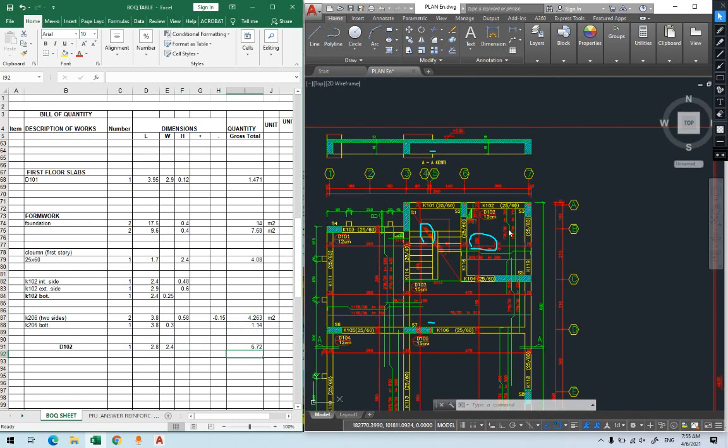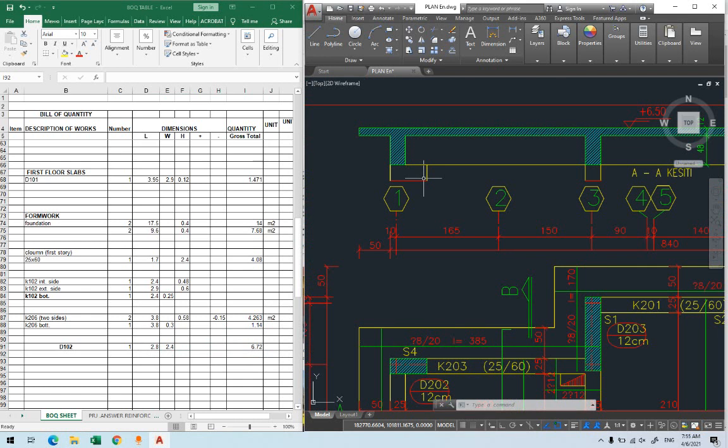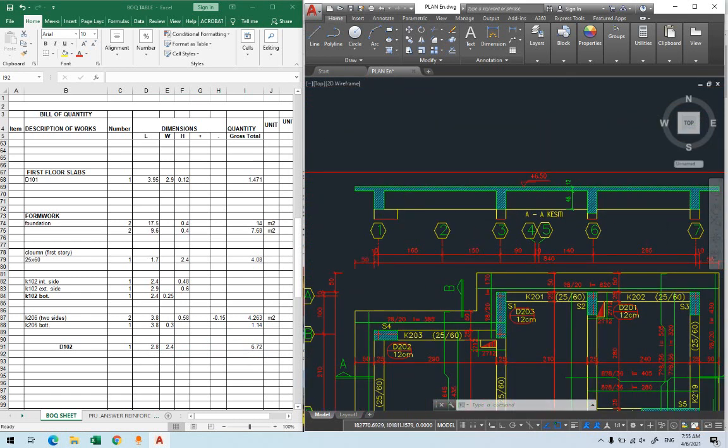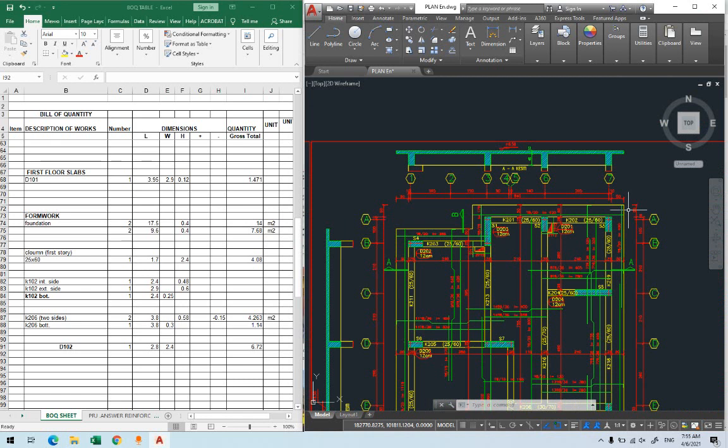Remember, under it. Now, if you remember for the second floor, where we talked about calculating this formwork, we said we only put formwork under the slab here. Now this part which is extra, you will treat the same way. You will put the formwork under here, and then you will put the formwork at this part here. Now in order to calculate this small part here, you have to take it from the plan. Now you will consider this one as the area.